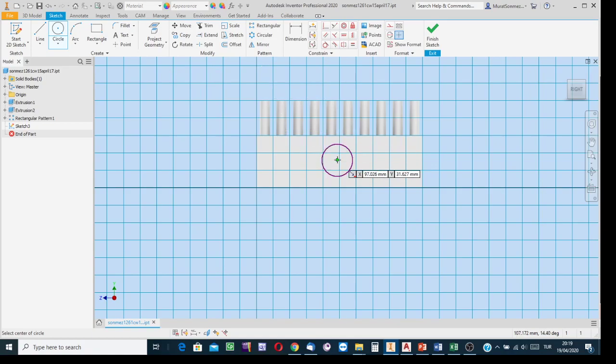I am going to anchor the center of this circle relative to this edge, relative to that edge. For having the projections of the edges, apply the project geometry process, indicate the edges and have their images, and then we can snap them. Indicate this boundary as the reference, indicate the circle. In this direction, say that the coordinate is 30.